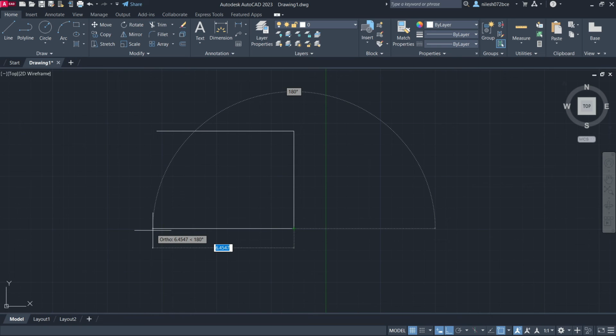I have to give distance for these things, but I do not want to give the distance, and I want to create that point there. So what should I do now? I should just turn it on and press my cursor here on this point, and now this will snap the point here. You can see if I provide my point here, it will be at the same point. You can see the rectangle has been created.